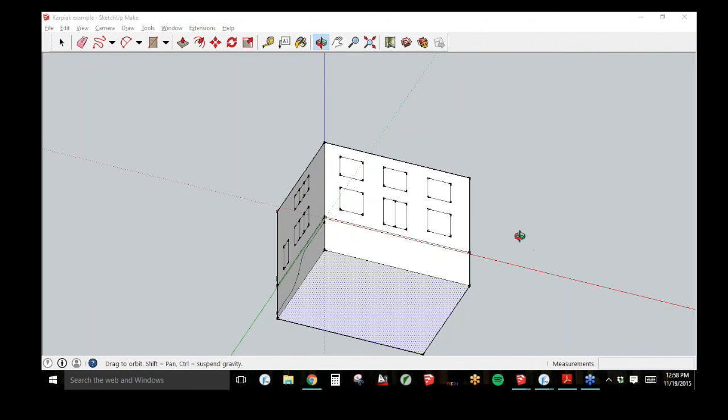Next question is, how are neighboring shading elements, i.e. buildings and trees, dealt with? You have to input those as either horizontal obstructions or just shading inputs on the static side. If you wanted to draw them in on the dynamic side, you could, to make it actually calculate in the model. But in the static side, you still have to tell it if there's a neighbor 30 feet away and the roof ridge is 30 feet above my window sill. You still have to input all of that.